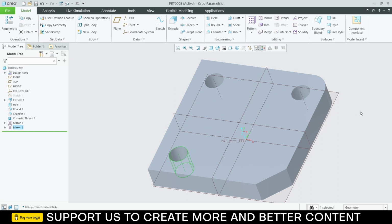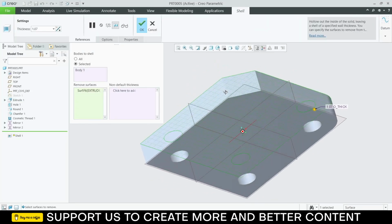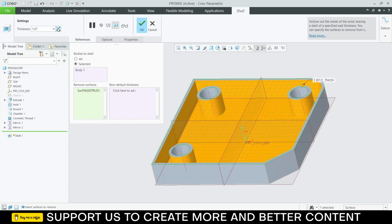Now we will also learn about shell command. I will select this top face. Click on shell. So as the shell says, it creates shell. So it will be a shell and the top is gone. Okay, you can increase or decrease the thickness, or you can change the orientation as per your requirements.